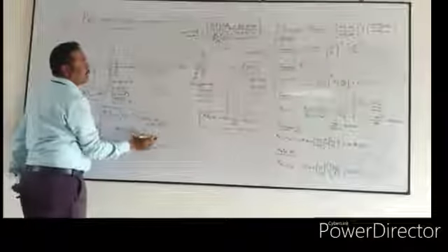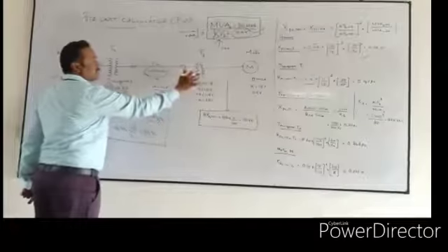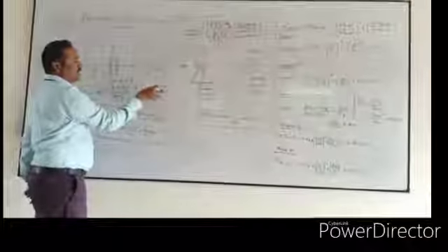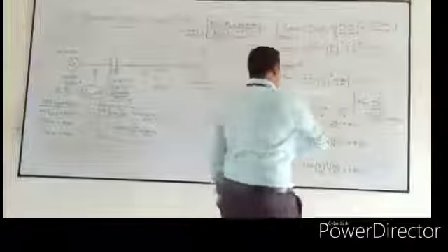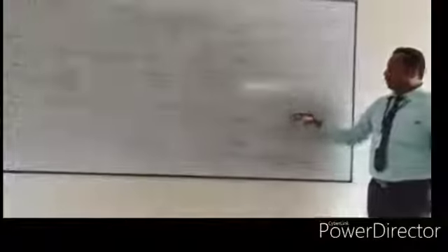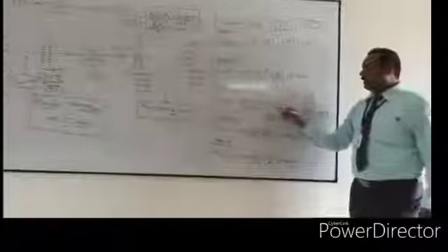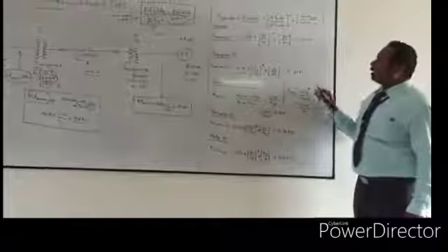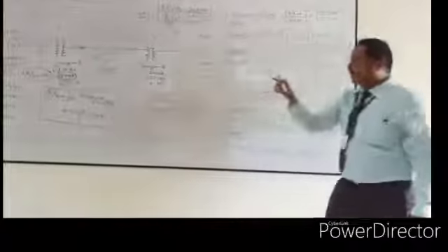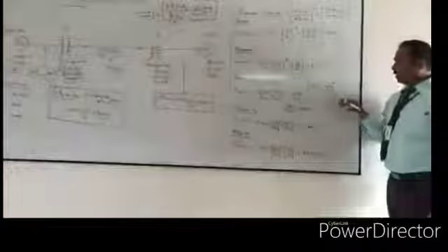This 100 kV can be applied for the primary side of this transformer T2 also. So now the new per unit value for this transmission line can be calculated like this. With the help of this formula, we can calculate per unit value as actual value by base value. So already I told you that this is actual value j100 by XB, and the formula for XB is kVp squared by MVAB, and kVp, just now we have calculated, this 100 kV is going to act as the new kVp. So 100 squared divided by 30, and finally you will get 333.33 ohm.